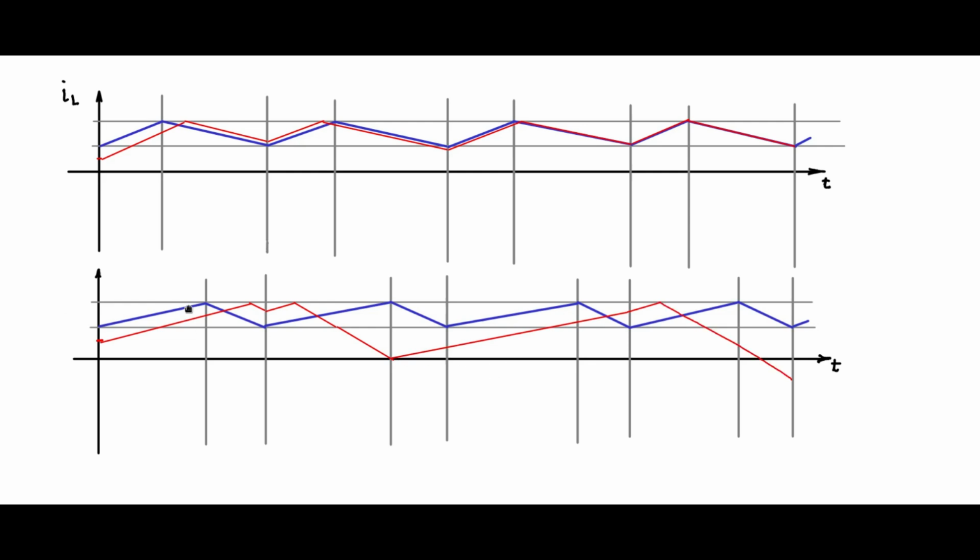And you see that the disturbance starts growing. Cycle by cycle it starts growing, it becomes unstable. So it never converges to the expected steady state value of the inductor current. So when the duty cycle is greater than 0.5, the inductor current will start diverging and it will not be stable when you do current controlled operation in this fashion, where this is the IL reference. The top of the inductor current ripple is the IL reference.